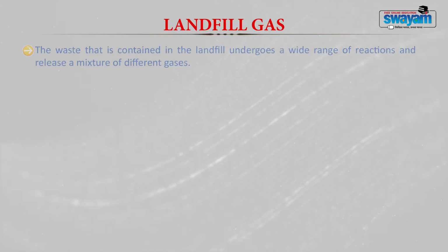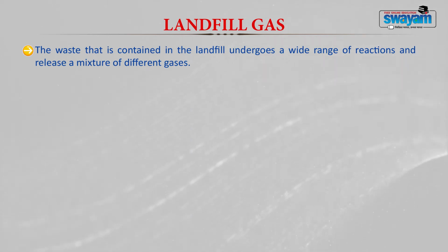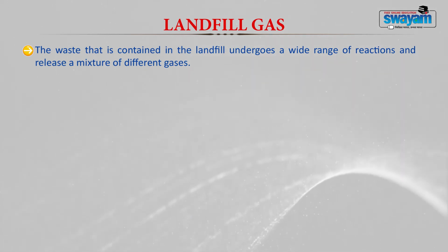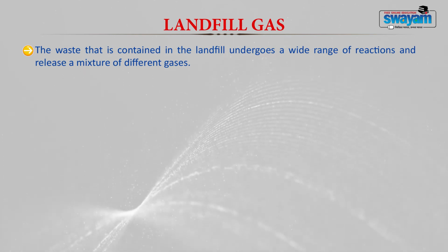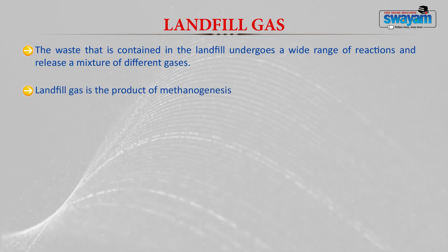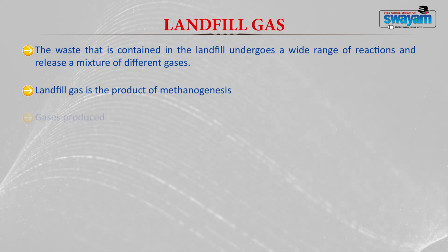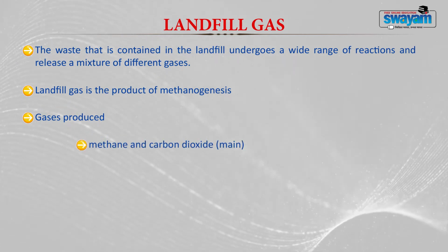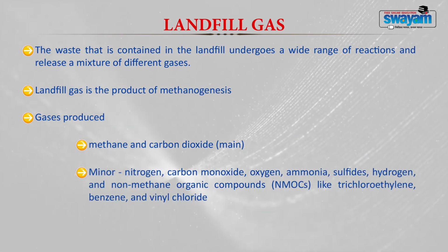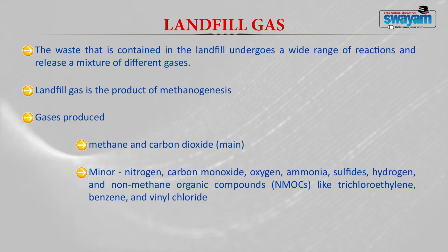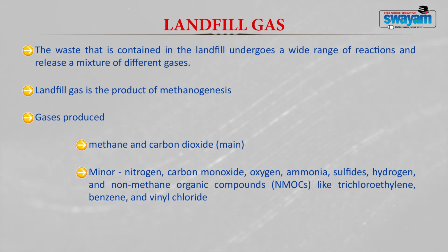Now, landfill gas is generated when the waste contained in the landfill undergoes a lot of reactions. During biological decomposition, they release a lot of gases. Landfill gas is a product of the methanogenic phase. The gases produced include methane and carbon dioxide, which are the major constituents of landfill gas, and the minor constituents are nitrogen, carbon monoxide, oxygen, ammonia, sulfides, hydrogen and other non-methane organic compounds like trichloroethylene, benzene and vinyl chloride.